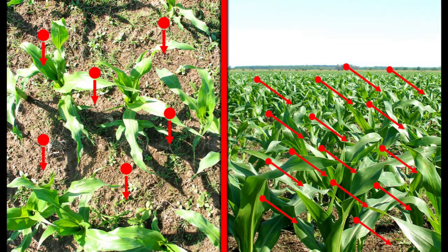Now those big droplets are going to tend to land on the first surface that they encounter. They're not going to be subject to any deviation of their trajectory due to wind or turbulence behind and below the aircraft. So they'll tend to impact on the upper or the outer parts of the foliage.